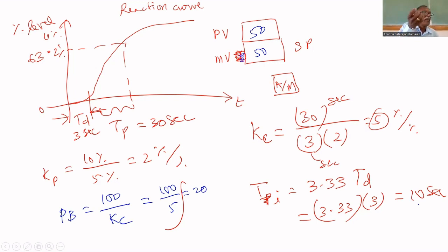After 3 hours, let us assume that some voltage is decreasing. What will happen to the flow rate? It will decrease. That's why the valve will open more to adjust the flow rate, so that again it will come to the 50% level. You understand that? That type of response is called regulatory response.